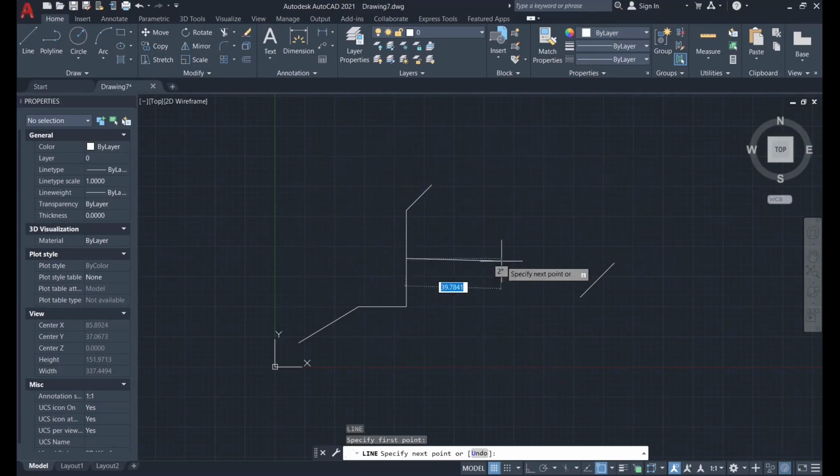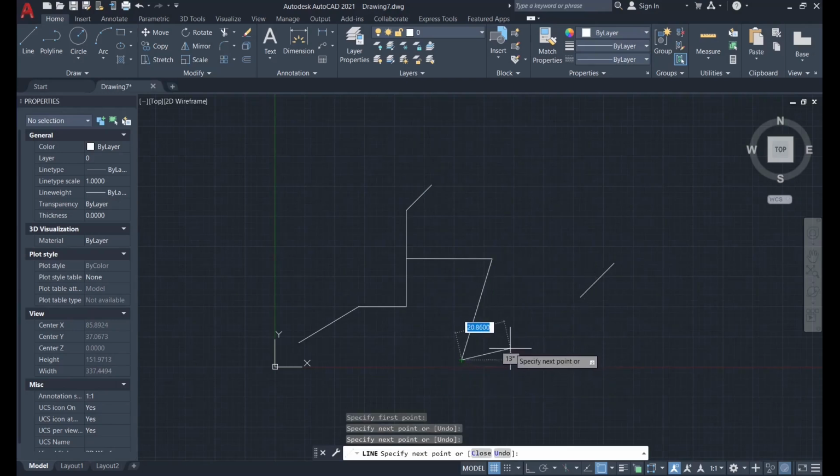This is very helpful when you want to draw lines without having to do this from many other commands using the Cartesian or the polar method. I would have to draw one line here, then remember the middle, draw the other one, and so on. Instead of that, I can use the snap and it shows me the middle.